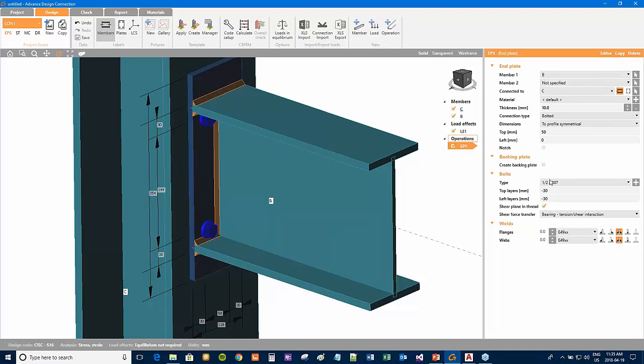After that, you have your bolts here. You can also define more bolts. You can play with the properties of your bolts from here. You can define the coordinates or location of bolts. For example, here I have -30 regarding the ends of my plates, but you can add more bolts and change the location of the bolts.